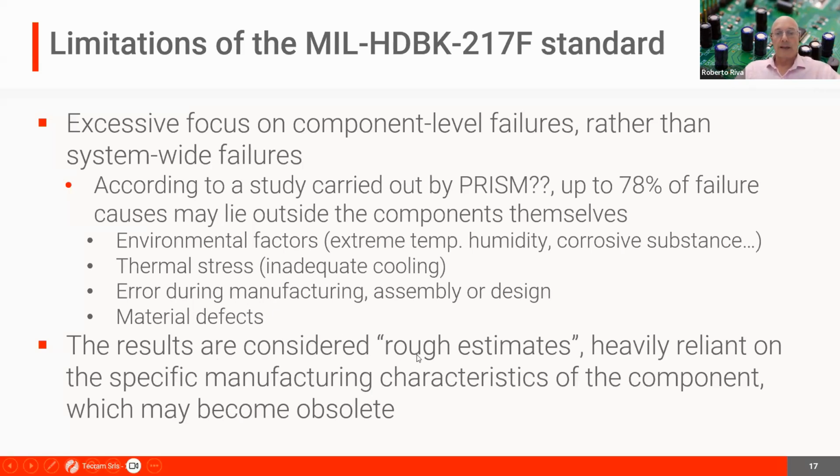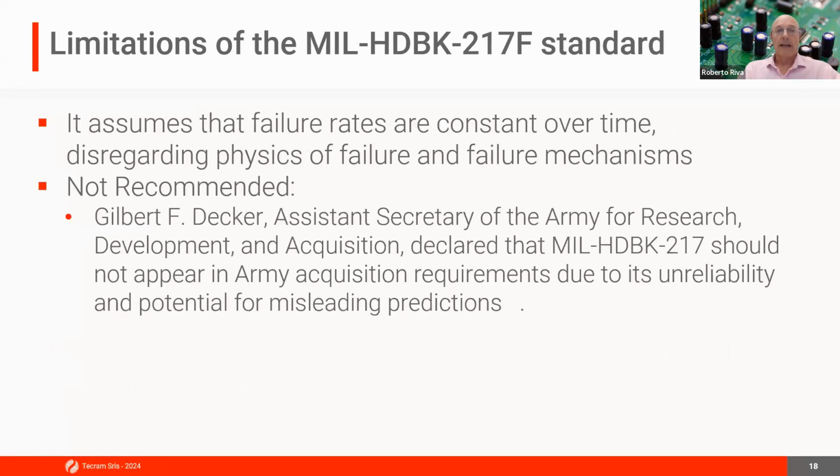And the results are therefore considered a rough estimate. They're heavily reliant on specific manufacturing characteristics of the component, which has become, not may become, has become obsolete. Another limitation is that it assumes the failure rate is constant over time, disregarding physics of failure and failure mechanisms. And it also ultimately ended up being not recommended.